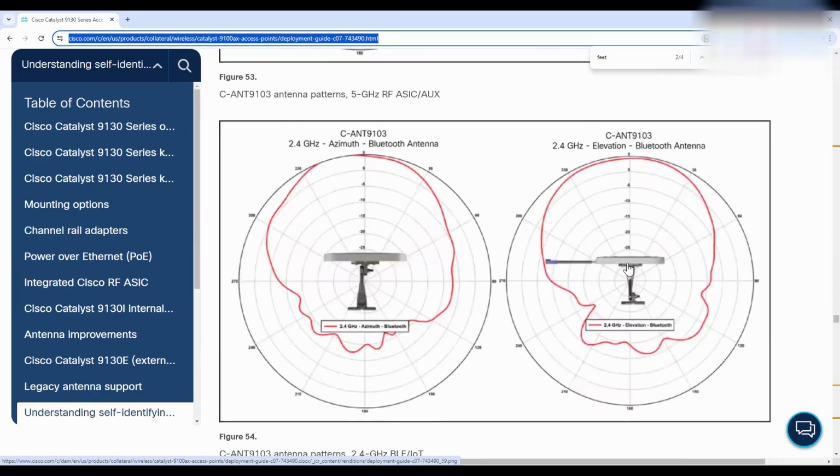see, if you keep it like this, inverted, it is going to normally cater in one direction like this, semi-directional. So whatever is in the backside, this lobe particularly, it is very less. Okay, this is an elevation. Elevation is nothing but when you're looking from the side. So as you can see, when you are keeping the AP like this, with the antenna on the top, it is going to send the signal in a unidirection, right? Like this. So we say unidirection, or the semi direction.